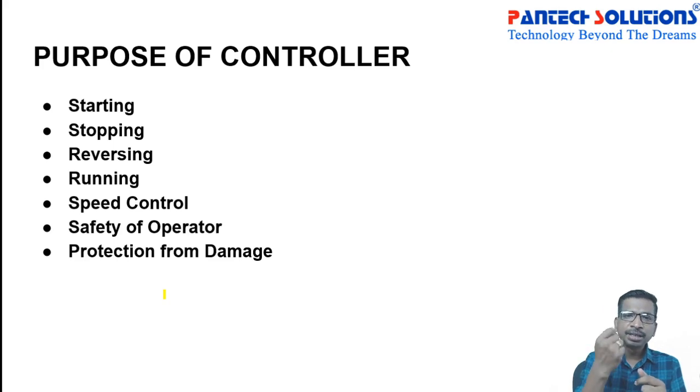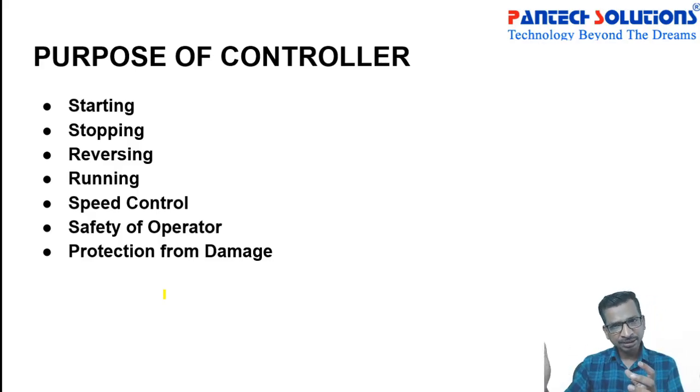So we have to constantly monitor the rotor or stator current. From the current behavior we can identify the insulation strength. So in an electric vehicle it is a critical parameter to identify the motor health also. So in that aspect your drive should support protecting the motor from faults.